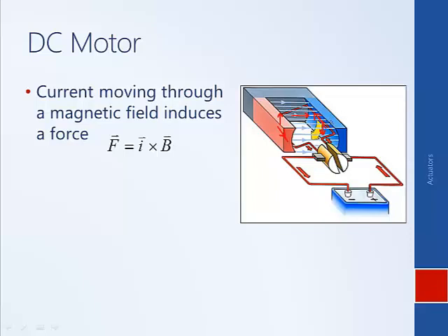You could imagine that it would want to make the coil flip back in the opposite direction. And so you wouldn't end up with a motor that's continuously spinning. In essence, the alternation of the forces would cause the coil in the middle to reach some equilibrium where it's basically just standing still. The way that this is addressed is that when the coil flips over, we need to switch the direction that the current is flowing through the coil.